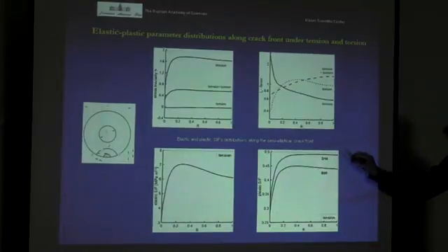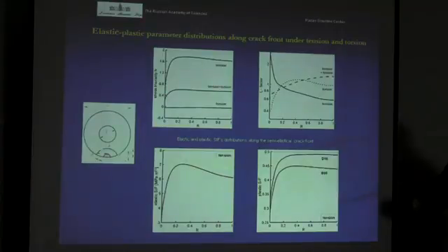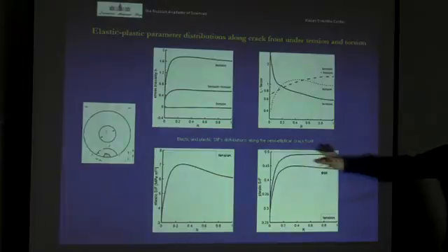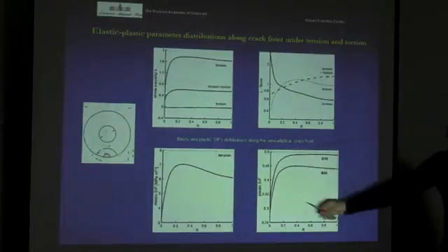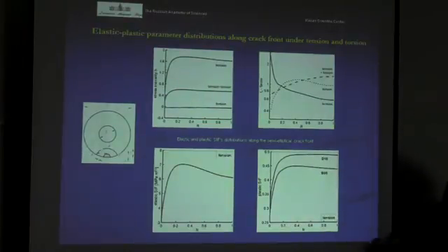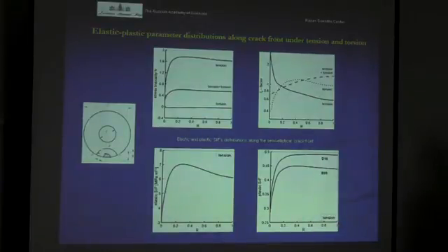And at the same time, for the same loading condition, you see for two aluminum alloys with different plastic properties different curves for the plastic stress intensity factor changing along the curvilinear crack front.